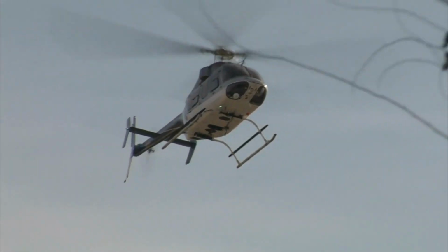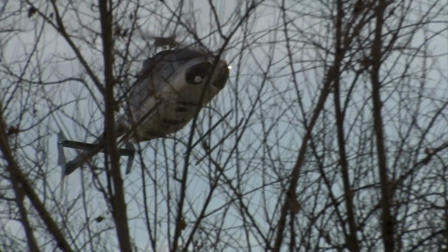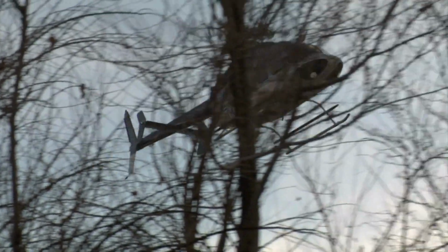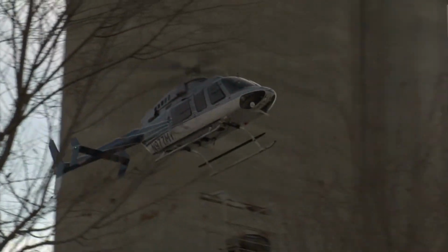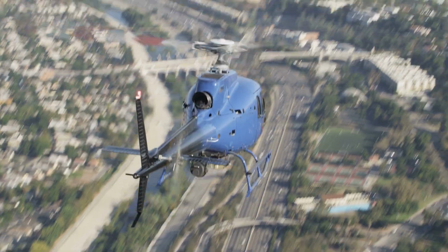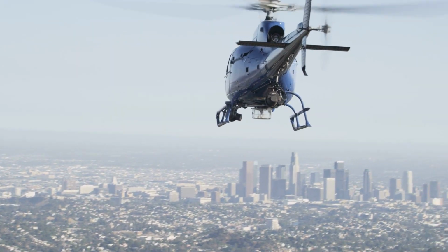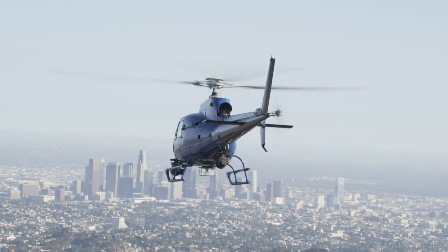Exaggerated cyclic movements, improper anti-torque pedal control, failure to maintain the desired hovering height, neglecting proper RPM, and overlooking the need for a clear area prior to the maneuver are pitfalls to avoid in this delicate process. In conclusion, mastering the art of rearward hovering flight allows the pilot to command a seamless operation in the sky.